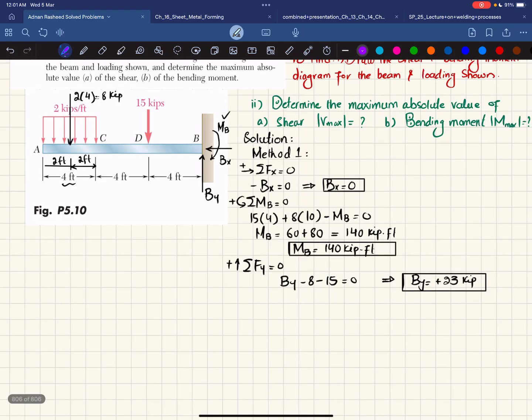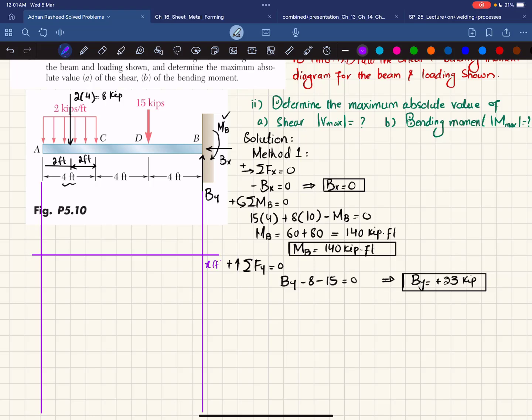For that I have to draw the vertical line from the end of this beam, just like here I will draw. Clear? The first thing that we will find is the shear force diagram. So again for that I have to draw a horizontal line, and to show length in feet. On the y-axis you have shear force having unit kips. Clear? Let's take one division equal to 5 kips, so it will be minus 5, minus 10, minus 15, minus 20, and minus 25.